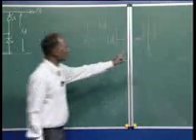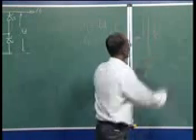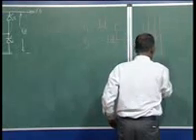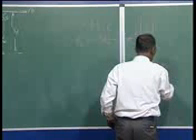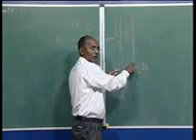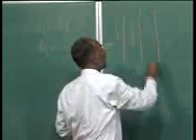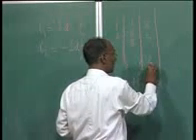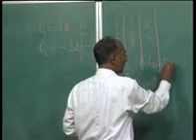Once 3 is fired, in this period the current I1 plus I3 is going to be ID, because this current is going to decrease and this current is going to increase, and finally once we are having 2, 3, this is over. At this period I3 is ID only, because 1 is off.